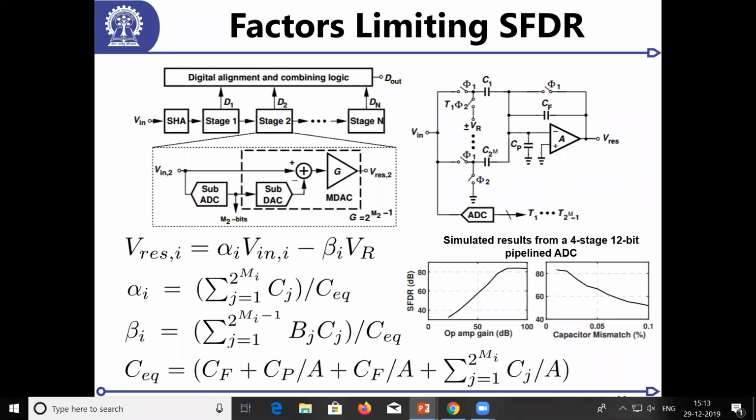So when a CD player is playing your music, inside there is a special circuit that adds dither to it, adds noise to it, and it enhances your performance. It quantizes. And in a CD player, it further needs that because this dither actually breaks a periodicity of something called a quantization noise. Quantization noise is periodic. Although it is called noise, it is periodic. I didn't have the time to get into the math of it, but it is periodic. The dither actually breaks the periodicity of the quantization noise.